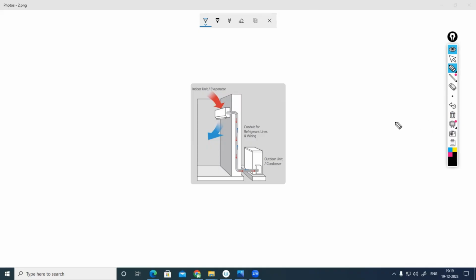See, in between the outdoor unit and indoor unit, what all connections will come? So remember, normally the electrical power point where we are providing, near to the outdoor unit, we can place in the bottom or in the top side as well. Doesn't matter. Okay, I will explain that. Anyhow, the power point we have to provide near to the indoor unit or near to the outdoor unit depends on the make. Depends on the make only.